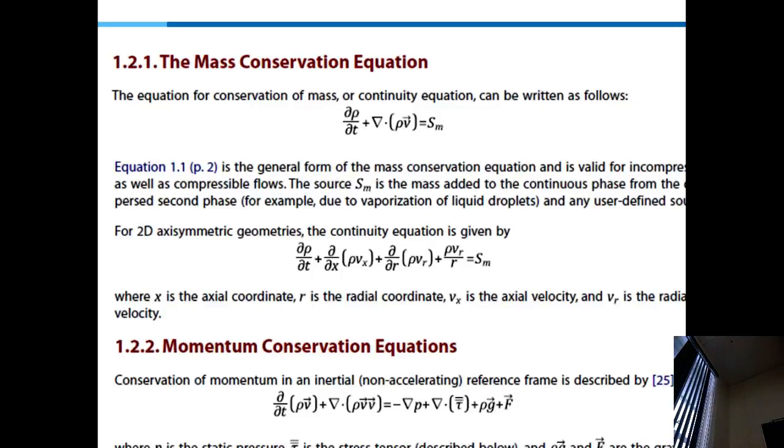If the physics doesn't have electrostatics, you can solve it as it is, just the Navier-Stokes equation. But if the physics has electrostatic interactions, then you can include them as a source term in here. That algorithm is essentially built on the Navier-Stokes equation, but it calls for a different set of computational schemes that tracks the interface, front tracking schemes or level set schemes.